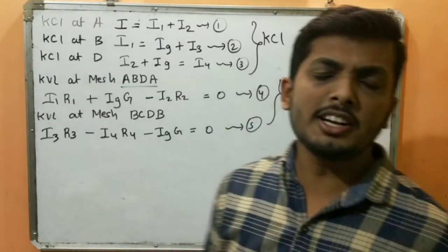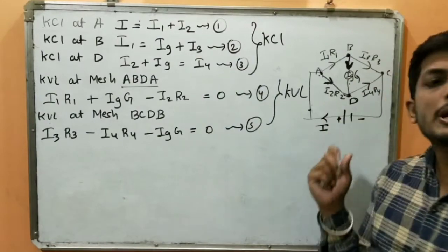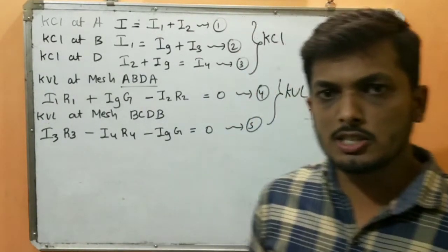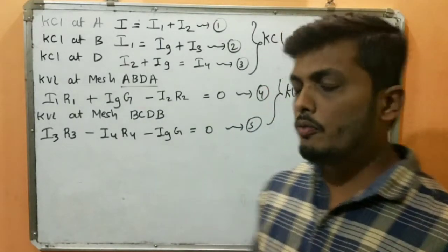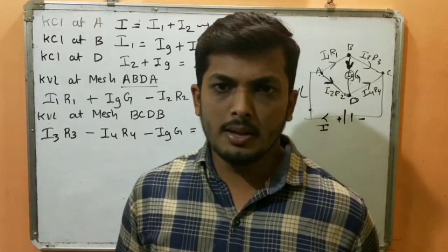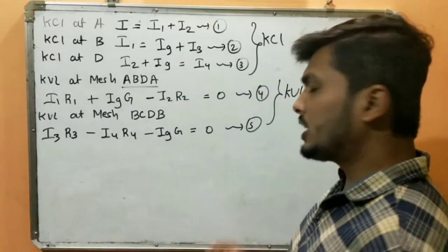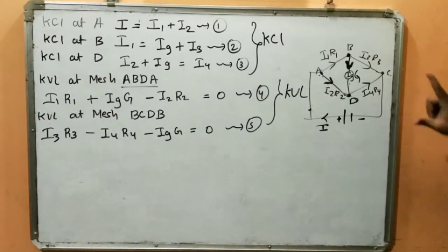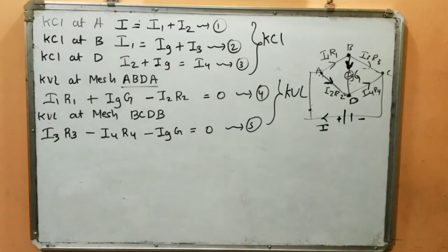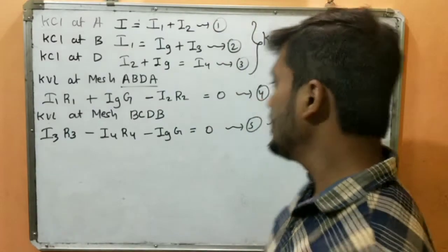So just understand Kirchhoff's current law and Kirchhoff's voltage law and simply apply them to this complex electrical network consisting of four resistors, out of which three are known and one is unknown. Now, as I told you, we are going to find the balancing condition, and you already know the formula. But to satisfy the balancing condition, I have told you earlier that the galvanometer reading should be 0. Once the galvanometer reading is 0, only then will the balancing condition be satisfied.